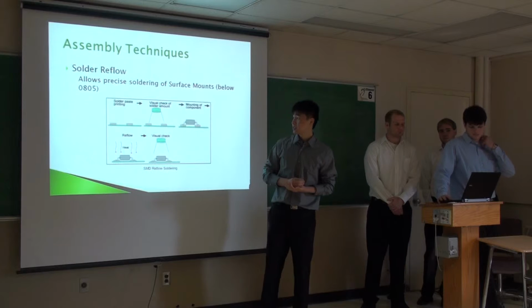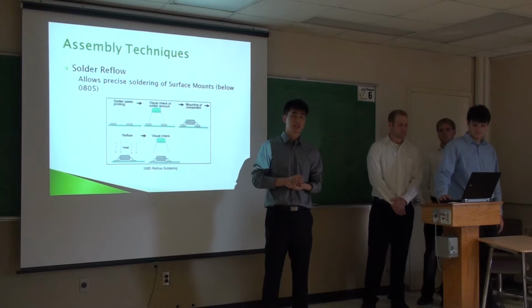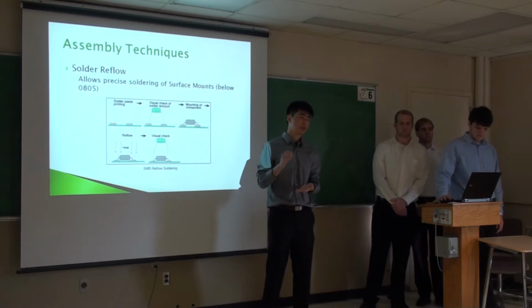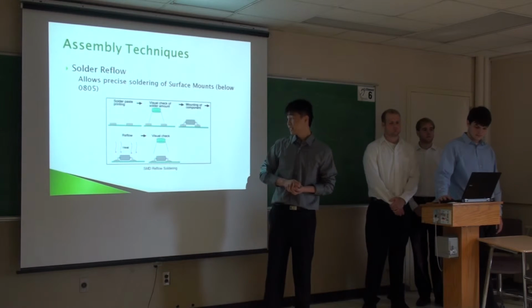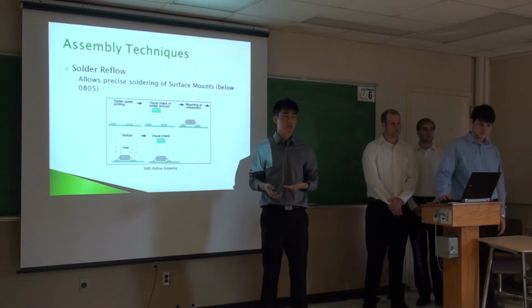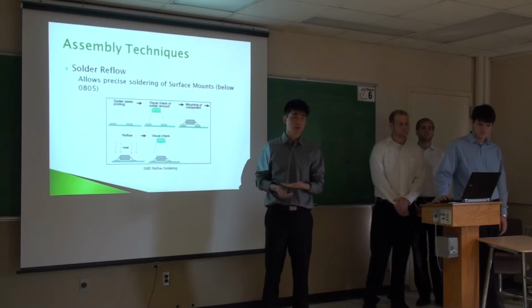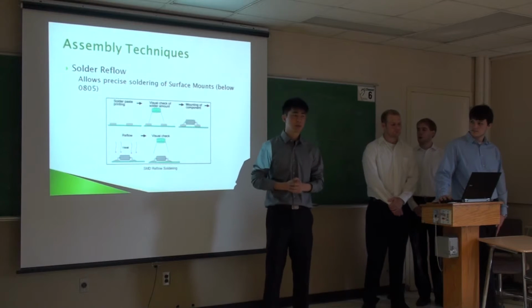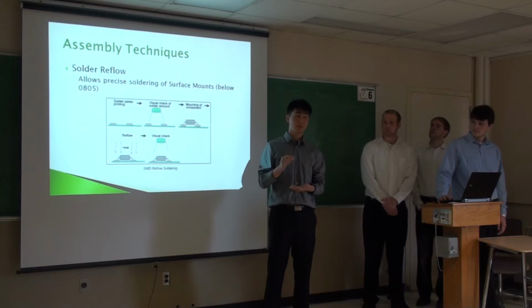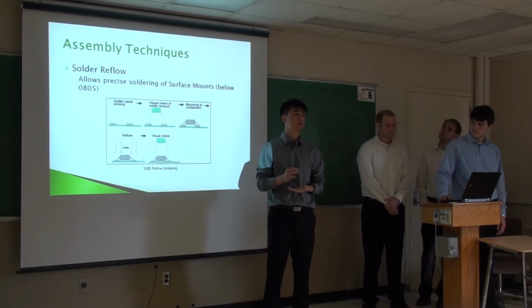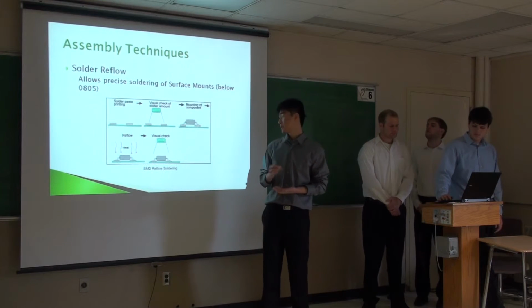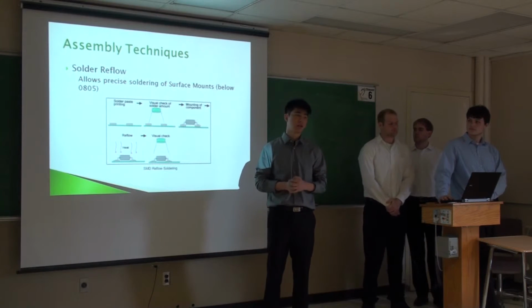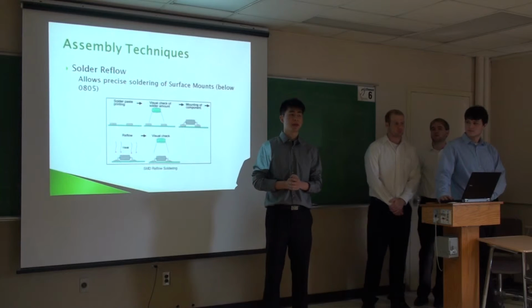The solder paste is placed on the pads, and after visually checking for a sufficient amount of solder, the component is mounted on the pads. Then after each component is put on the PC board, the entire board is loaded into the soldering oven and baked. After reaching a certain temperature, the solder paste melts, or so-called reflows, which makes the joints. So solder reflow is much more complex and expensive, but it allows very dense surface mount packages.